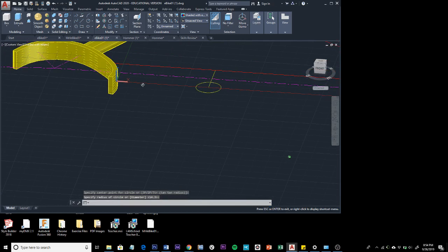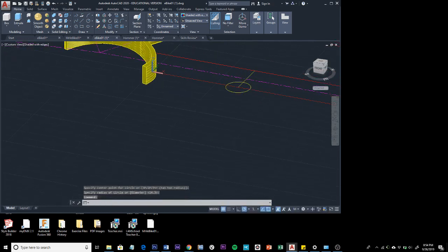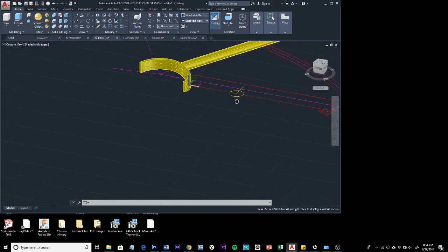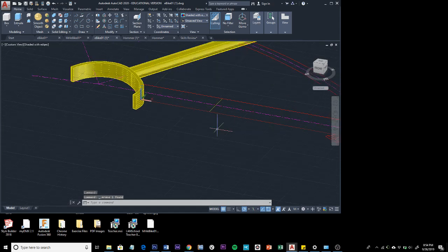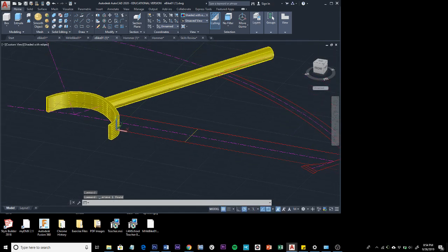again, we have the same problem that we had before. If I extruded this circle, I can only extrude it on the x-axis, so it would be extruding in the wrong direction. So I need to rotate my UCS on Y again to get Z lined up with this line. So I'm going to delete this circle. And then we need to rotate our UCS.